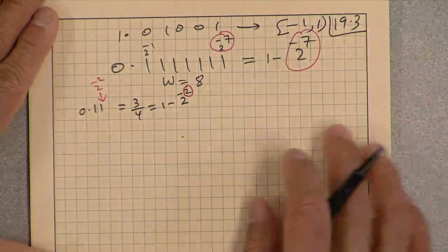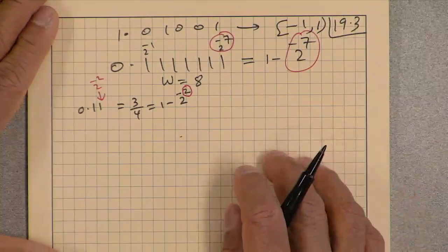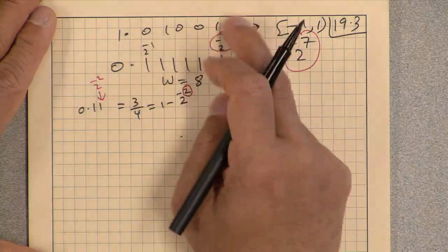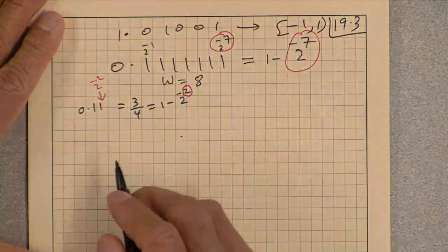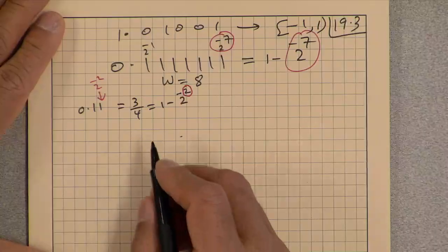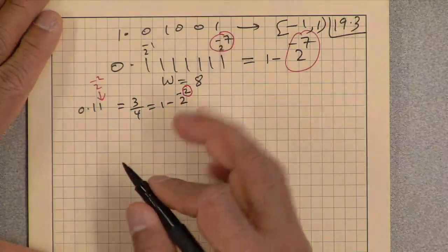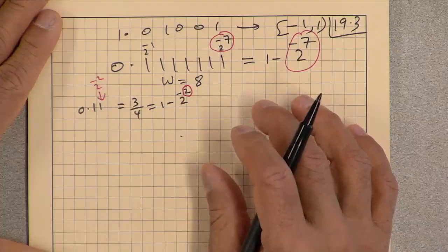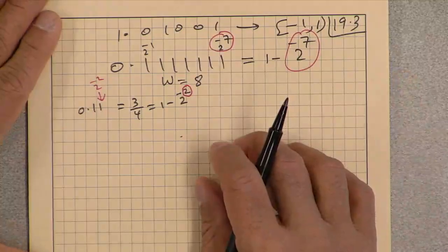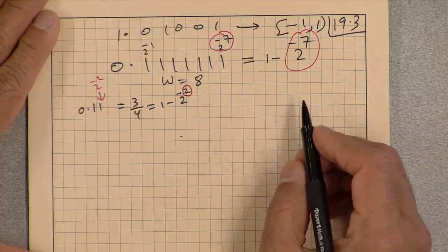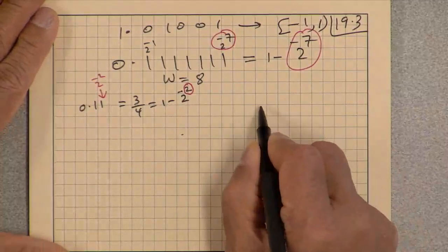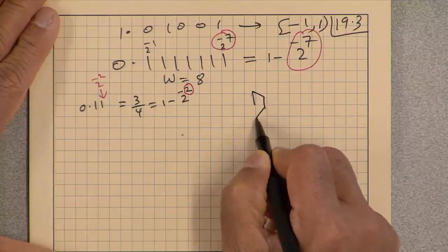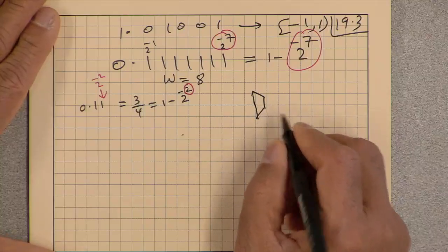So it doesn't make sense, when we are realizing in hardware, to multiply something by 1, even though we are not representing that. That's not really what circuits do, right? When the coefficient is 1, you have a bypass. So when the coefficient is exactly 1, you bypass the multiplier and don't multiply anything. That's essentially a bypass operation. So you check if the coefficient is 1, and you have a select signal.